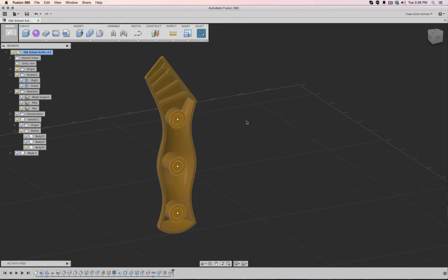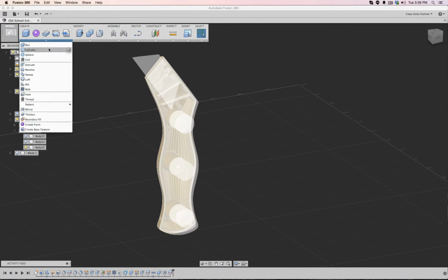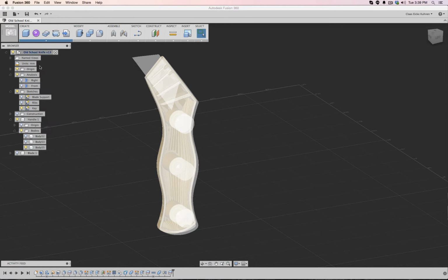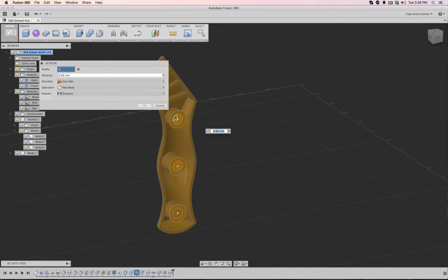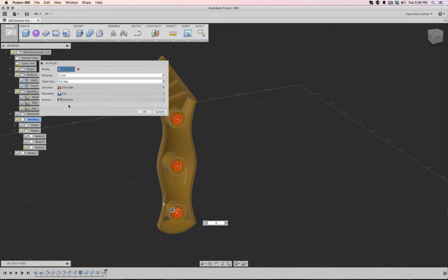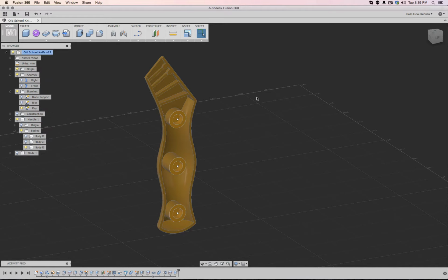So what's the advantage? One thing actually, if I change the rib on my half, this other mirror part will get updated. So think about all the interactivity, how you could automate tasks. What I can do here now is go into extrude and say this circle and this one, move in, let's say 5 millimeters and cut. Okay.